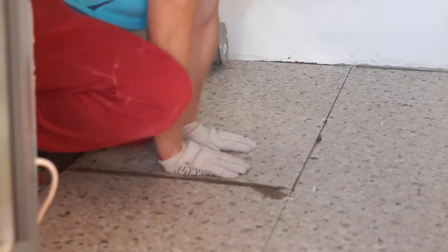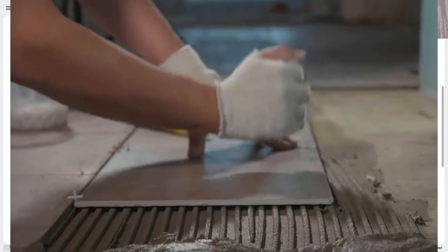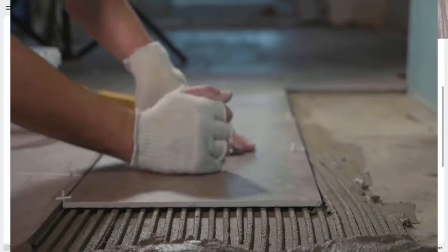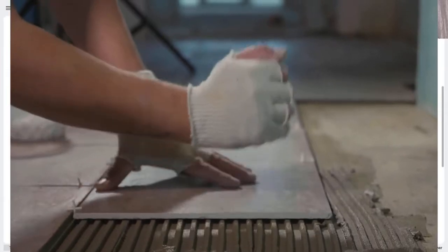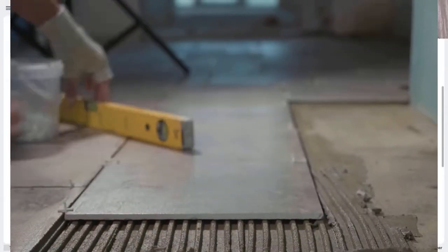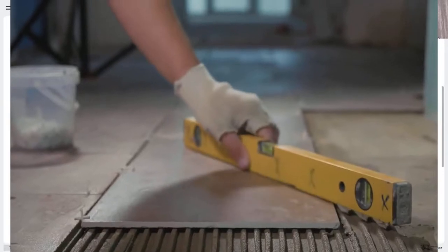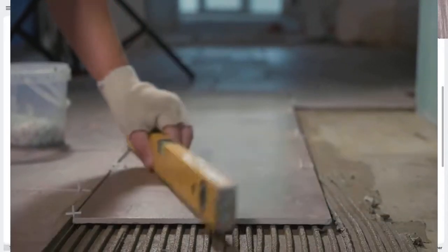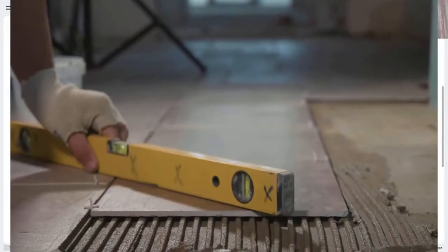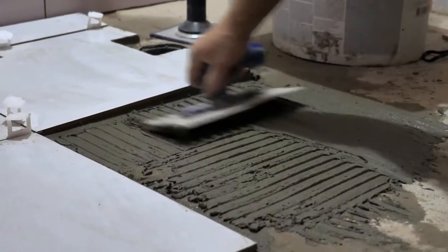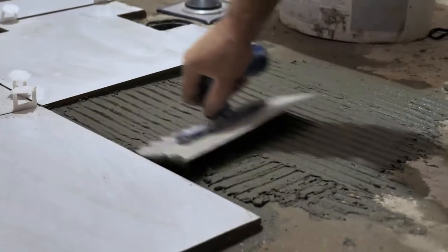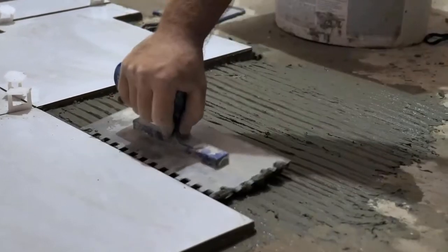So why are we providing it? To accommodate dimensional variation. See, the tiles whatever we are getting are not exactly the same shape or size. There is always a dimensional tolerance as per IS 15622. So to minimize that dimensional tolerance, we are providing the gap, then for expansion and contraction, and the installation tolerance. So these are about why, and what are the tiling joints.